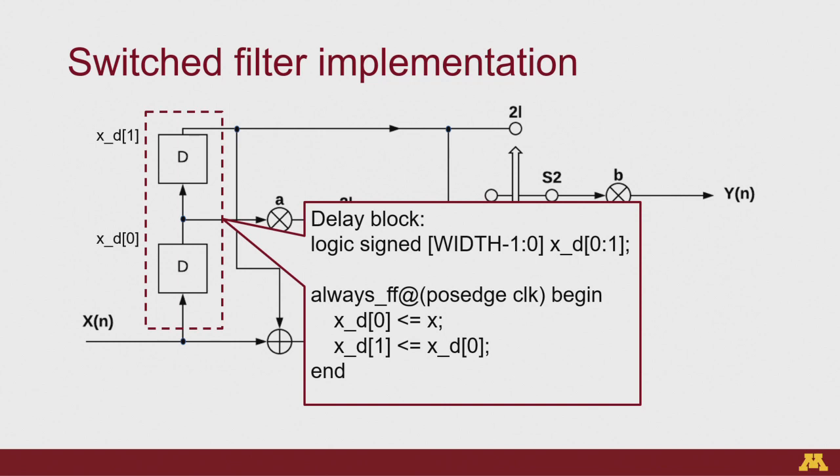What we are actually doing here is, when we have these variables, we are just physically naming these wires. So you can imagine that this wire in between these 2 delay elements is just going to be xd0, and this wire after the second delay element is going to be xd1. Does that make sense? That's literally the physical representation of the variables in Verilog. They represent the wire connections between these different blocks.